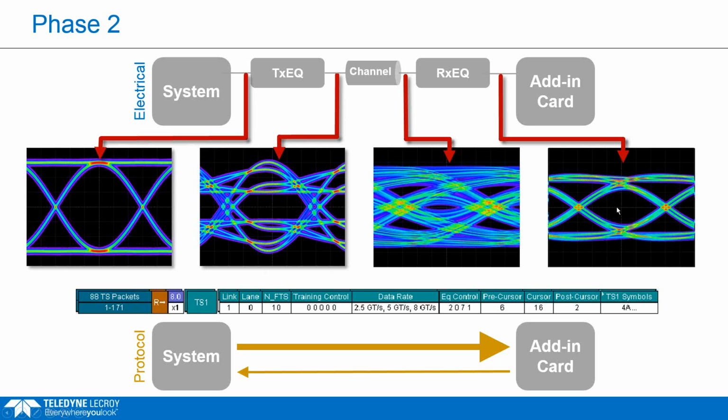Also, is the equalization process only done at power up, or is it done dynamically? They keep track of the BER dynamically, and if the BER becomes unacceptable, it starts a new sequence, for example as the equipment warms up. Yeah, good question. Is the equalization done only on power up, or is it done throughout operation?